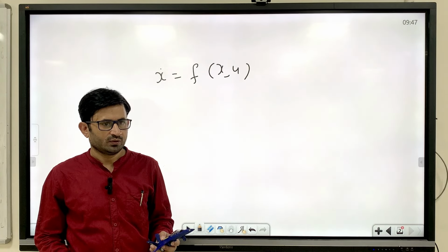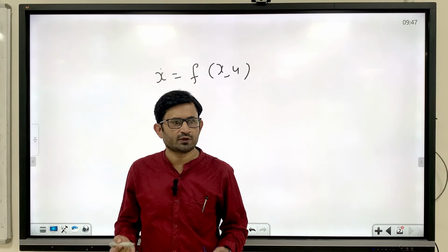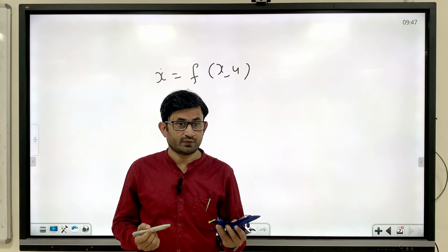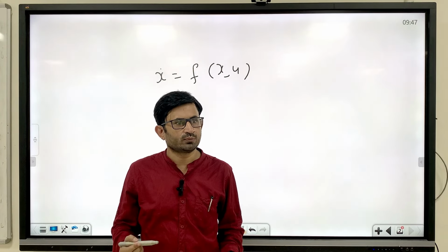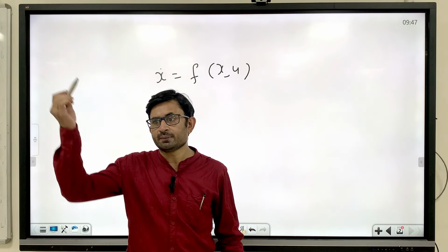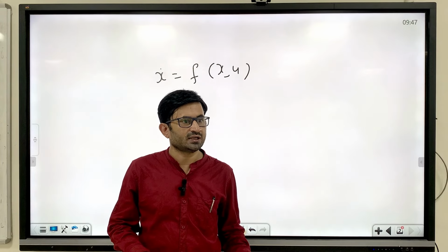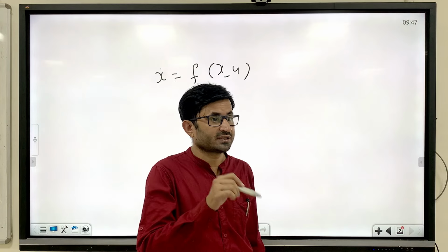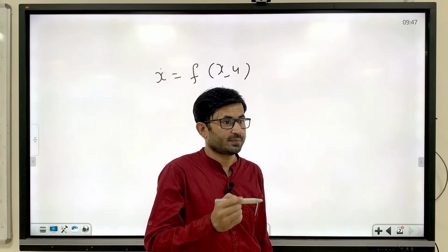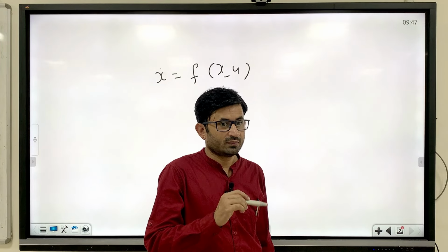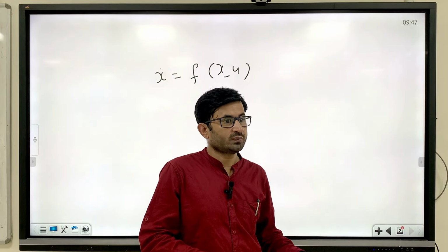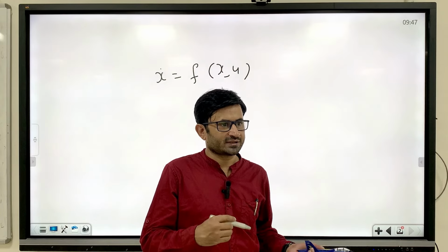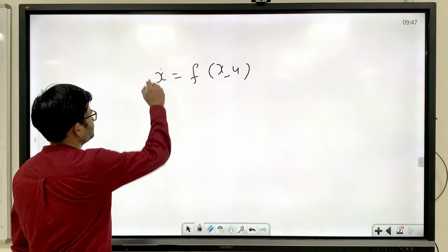Please note here, why I have written x dot, y dot, z dot. How is it different from u, v, w? Because x dot is also velocity, y dot is also velocity, z dot is also velocity, and u, v, w is also velocity. But u, v, w are in the body frame, but x dot, y dot, z dot are in the inertial frame. So you have to transform from body to inertial. Everything you can measure in the inertial frame. Newton's law is applicable in which frame? Inertial frame. The moment you measure in the body frame, it will change, right? That is why you define the three angles, phi, theta, psi, in order to transform from body to inertial, inertial to body. Next class we will derive the same.